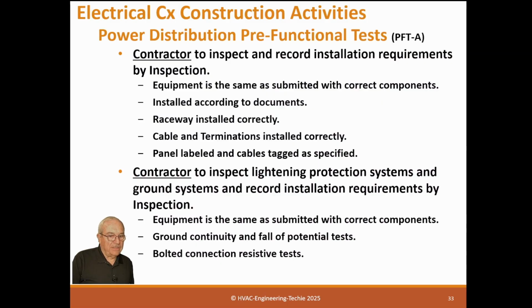They drill a hole and put a perforated pipe sleeve down in it. Then they put the ground rod down, and then they fill it with salt. And then they pour water on it until all that salt dissolves, and then they backfill it.